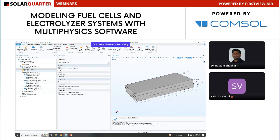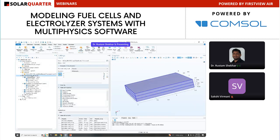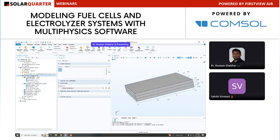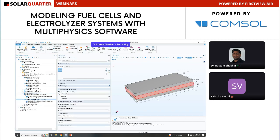So I will get the geometry which I want to work on. And now here you can add the material. I'll right click and say add material from library. You can see the materials available for that. I'll add the PEM fuel cell, so Nafion I'm adding. Okay, so now we have some default nodes. I can add the functional layers like membrane, I can add the H2 gas diffusion electrode, I can add the O2 gas diffusion electrode, and now I can assign those domains. The membrane is the central part, O2 is at the bottom, and then H2 at the top part.